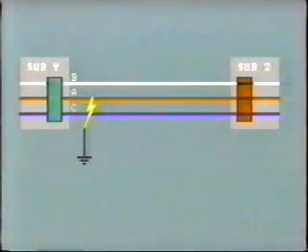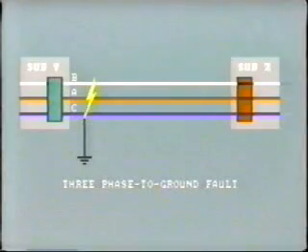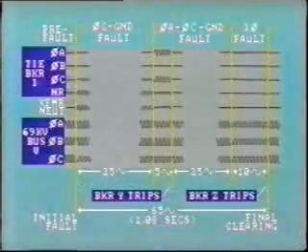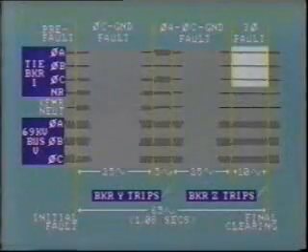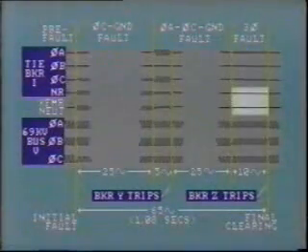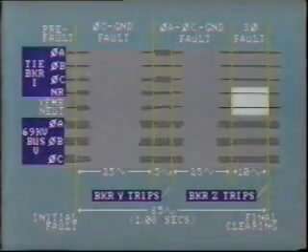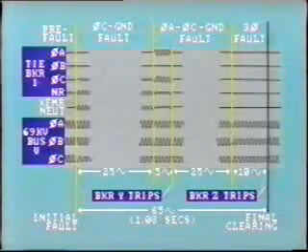At this point, the fault again changes. The A phase conductor now burns open. The tree contacts B phase and falls to the ground. But all 3 open conductors are now in contact with ground, resulting in a three-phase to ground fault. For the next 10 cycles, we have a balanced three-phase fault. You can see this from the three fault currents in the tie breaker and the fact that neutral and residual currents are now zero. Breaker Z at the other end of the faulted line now trips to completely clear the fault.